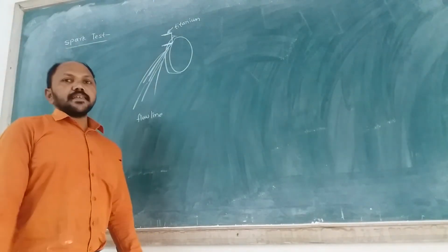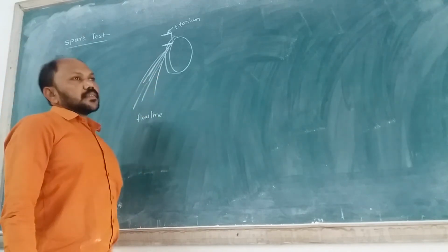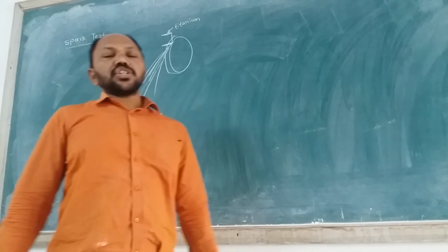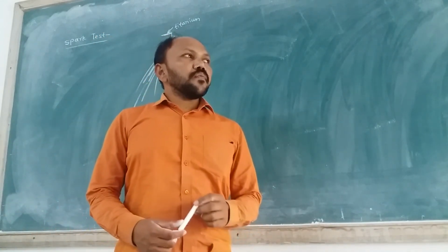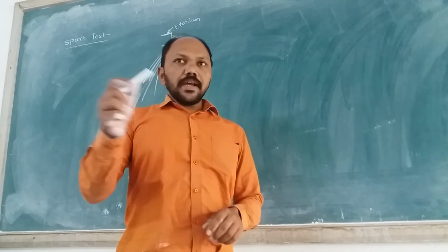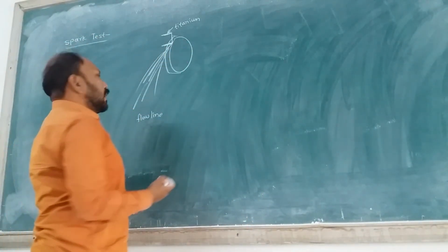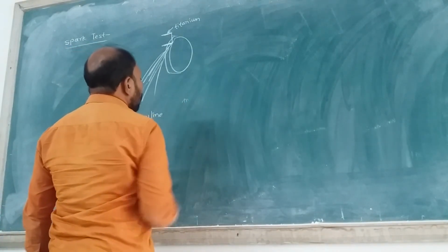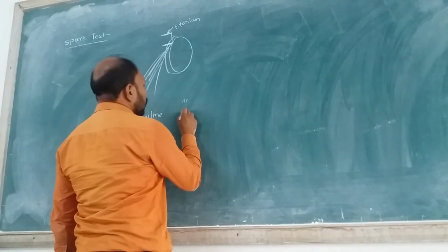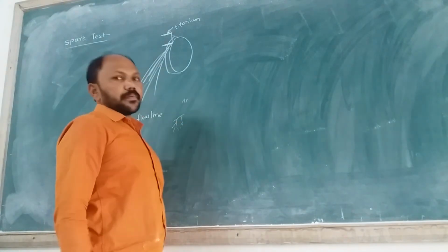If we take the example of titanium, in case of titanium material which is made with the help of a forging operation, it gives us flow lines. Okay, so this becomes the flow lines, and here flaws or bursts are not present, like these branches are not present.